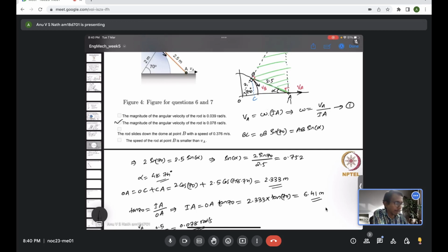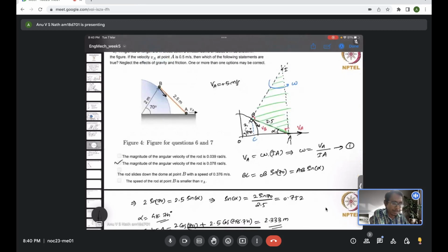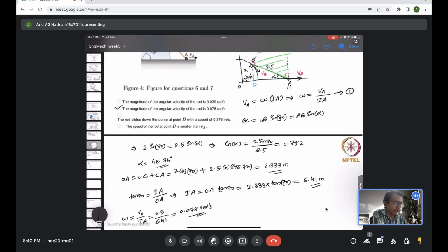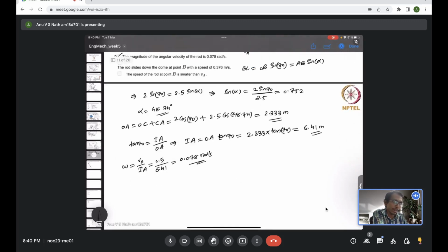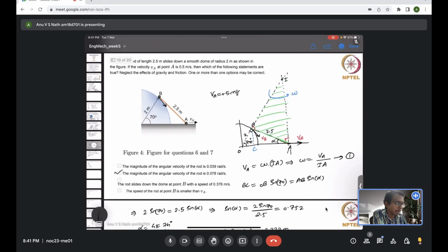Now the velocity of B, the point B, we need to evaluate. So again, the point B is in the same member as AB, which is forming like a rigid object, like an imaginary object ABI, right? So it's belonging to that particular object. So velocity of B, we can just write as the angular velocity of that particular member times the distance to the point B from its instantaneous center, which is IB.